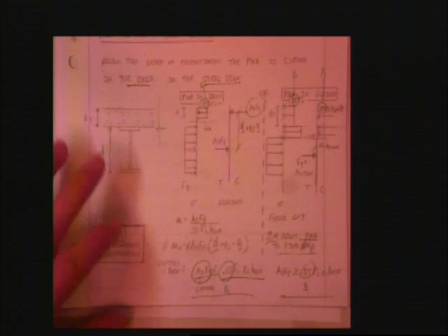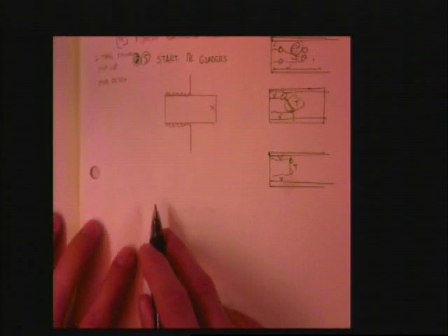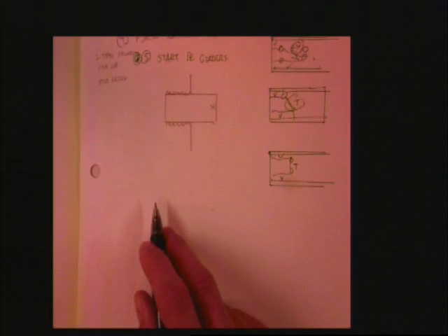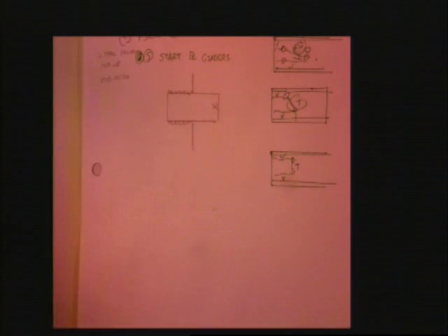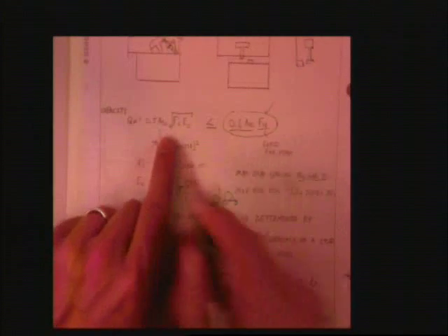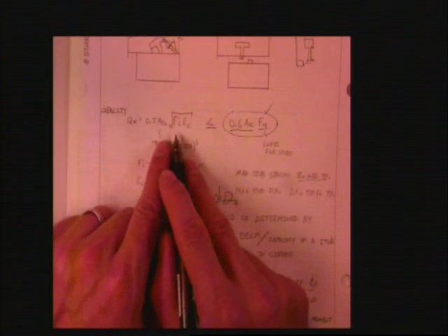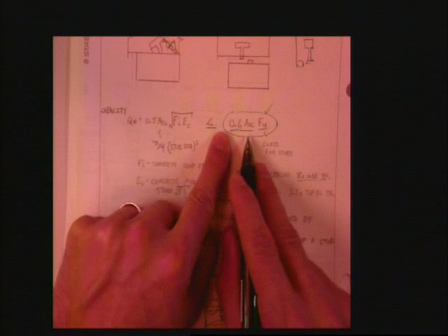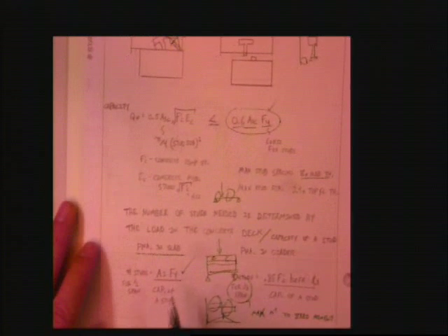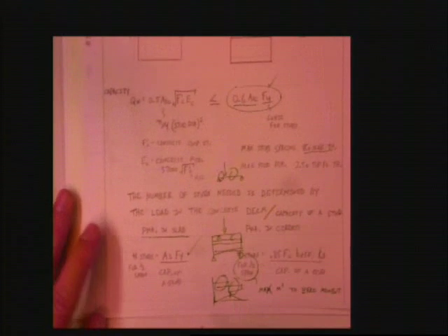Okay. Great. Now, when it comes to studs failing, there's two ways a stud can fail. Stud can either fail in shear. What's the other way? Concrete can fail, right? We have some equations that we use to calculate that. This is basically the concrete failure. This is basically the stud failing in shear. Okay, great. We have some limits on maximum stud spacing.